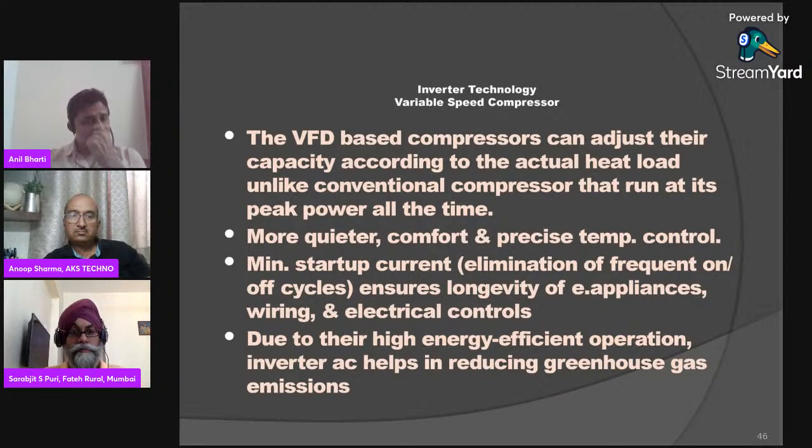अब क्या होता है कि जो नॉर्मल एसी है, जब वो स्टार्ट होता है, स्टार्टिंग करंट उसका 30 एम्पियर्स है, और 30 एम्पियर करंट अगर इलेक्ट्रिकल बंदा हो तो उसको पता होता है कि it is a huge amount of करंट। 30 एम्पियर करंट इतना होता है कि आपके पूरे घर को ऐसे हिला के रख देगा, जैसे भूचाल आ जाता है। आपका टीवी चल रहा है तो उसमें भी फ्लक्चुएशन आ जाएगी, आपकी लाइट, फैन, सब हिल जाएगा एक बार। It will pose a lot of stresses on your wiring, on your equipments, on your other equipments. लेकिन जो VFD बेस्ड कंप्रेसर है, इसका स्टार्टिंग करंट सिर्फ 6 एम्पियर से स्टार्ट होगा। It starts very slowly by taking a very small amount of current, 6 ampere, then 7 ampere, then 8, 10 to 13, 14, इस तरह से। तो इसके अंदर फ्लक्चुएशन नहीं होगी किसी तरह की। तो अल्टीमेटली it is very safe for your electrical appliances, for your household wiring and everything.